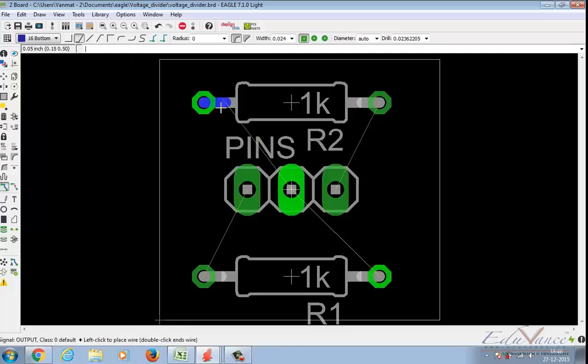So when you start routing, your wire will appear like this. This is your path. Sorry, not wire, your path. Now observe closely. When I select a node or a junction from where I want to begin connections, the yellow wire is constantly prompting where it has to be connected. If I move it around, even outside the board, it is still prompting where I am supposed to connect this.